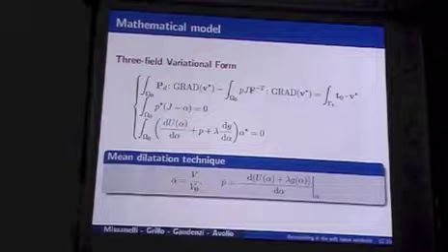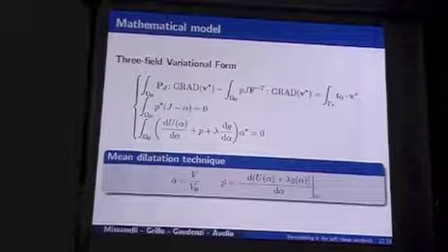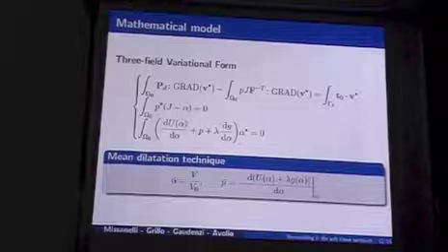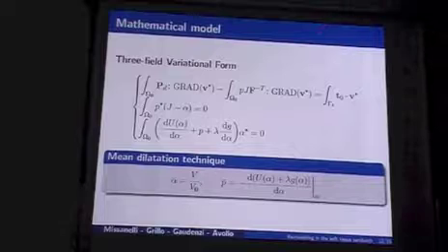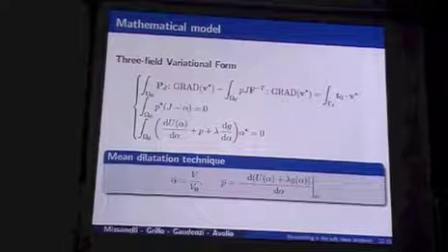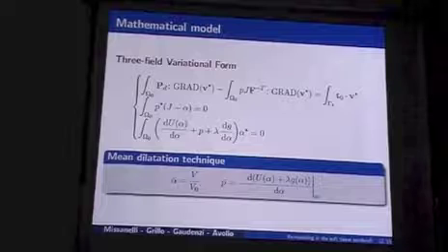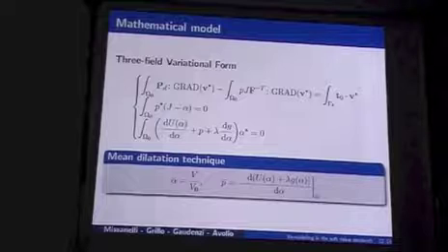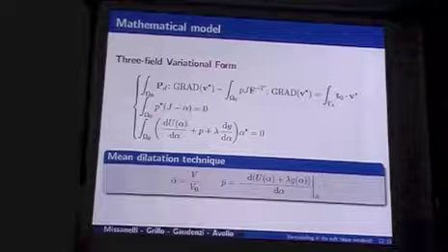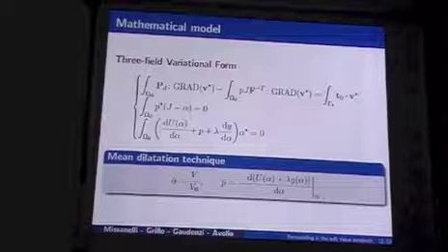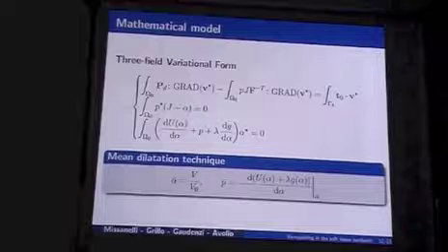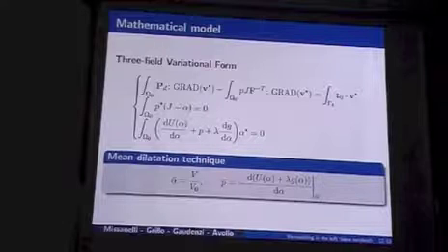we had this part that let us use an augmented Lagrange method. In particular, this is the parameter corresponding. And if you use a finite element with a low order polynomial interpolation, then you can get some numerical problems like locking phenomena. In this case, there are two techniques possible.